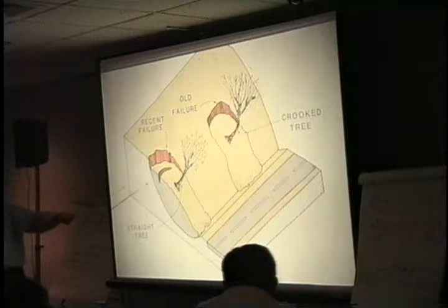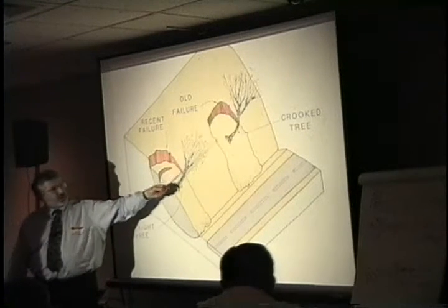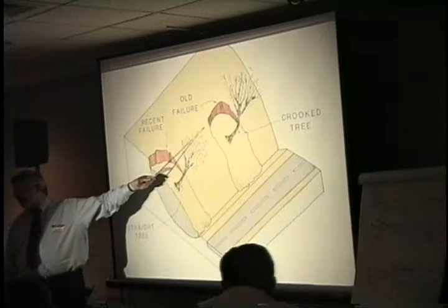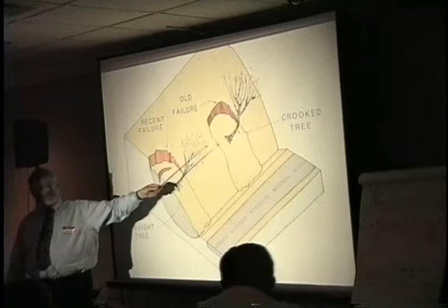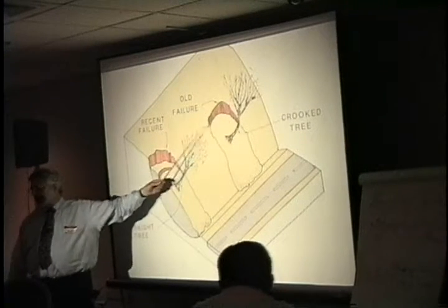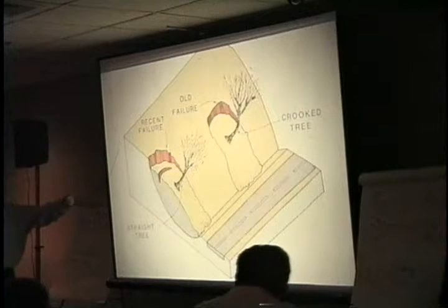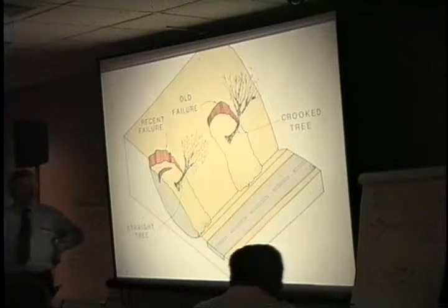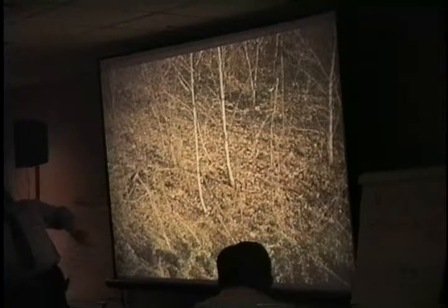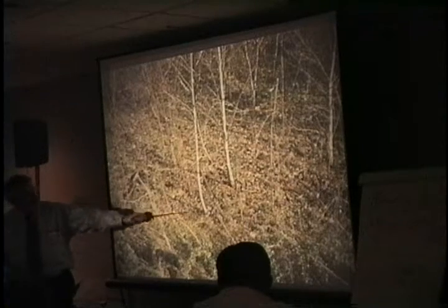If you got those bent trees and it's not just a bulge and a shallow slide, you got to think, use that as a tip, that this is a bigger problem than a little area. Especially if you look at the size of the tree, you can estimate the age. Okay, that's a fairly young tree, but it's got a bend in the base.